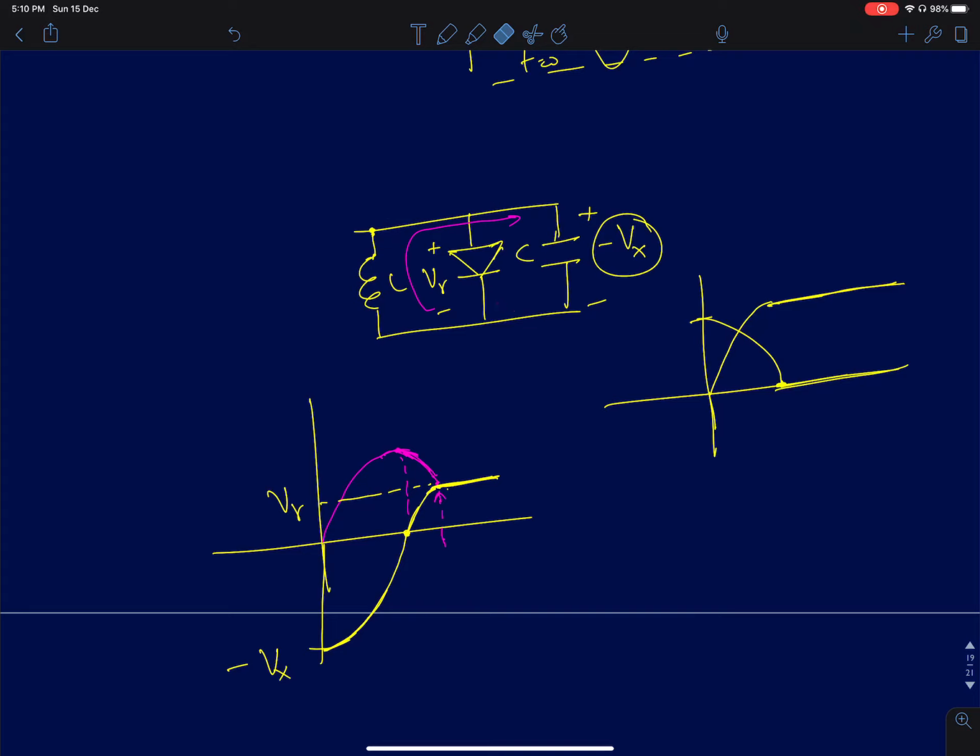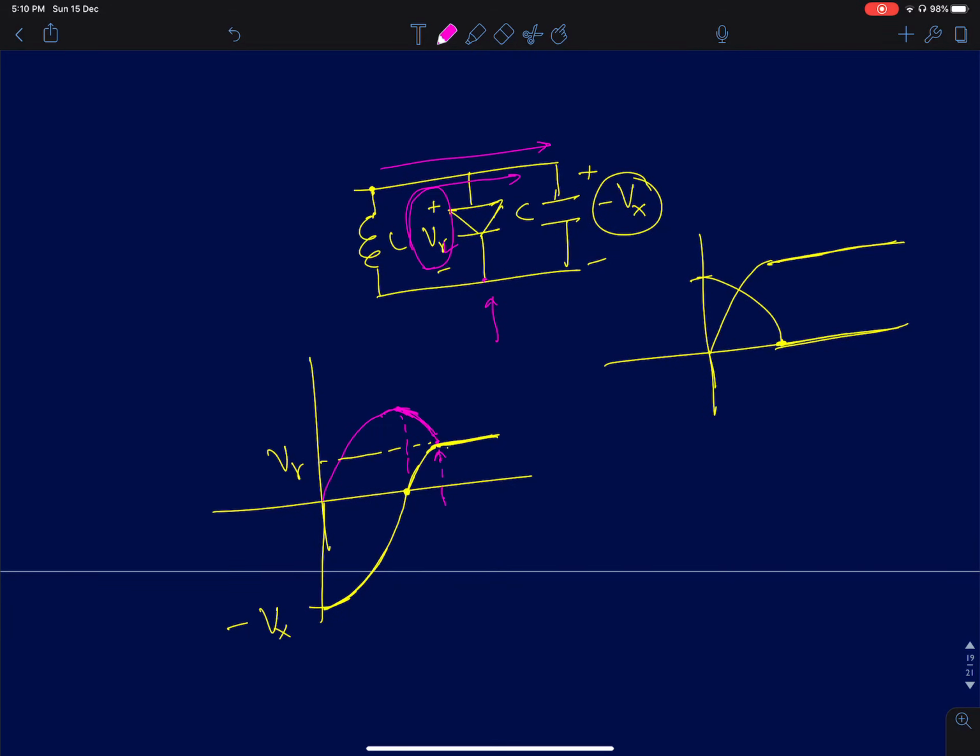So you should look at it intuitively. If any amount of current flows through the capacitor, then the voltage across the capacitor will increase. It will go above V gamma. But the diode won't let that happen, right? So it has to draw in all the current to stop that from happening. And that's what it will do. So the diode will now start taking current in this direction. Now, if there is a finite amount of current flowing in the diode, then there is some amount of energy getting lost. So now we'll look at the profile of the current across the inductor.